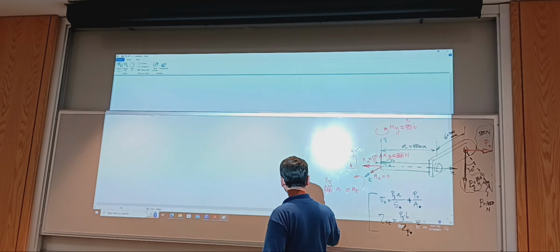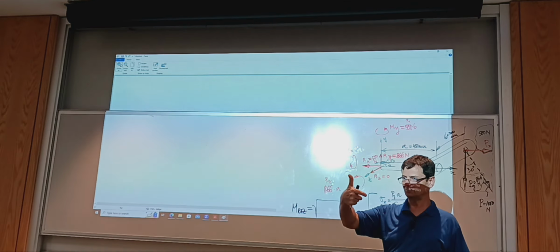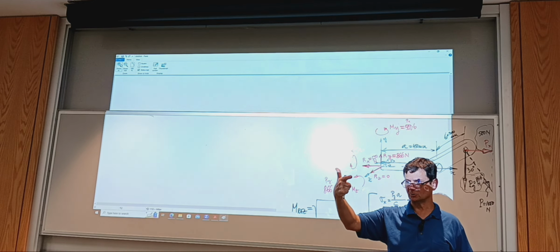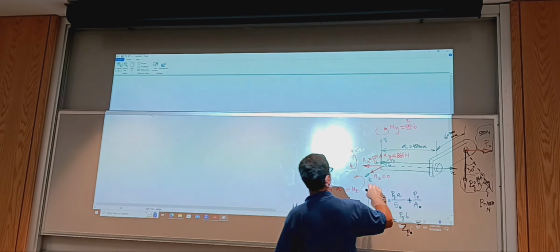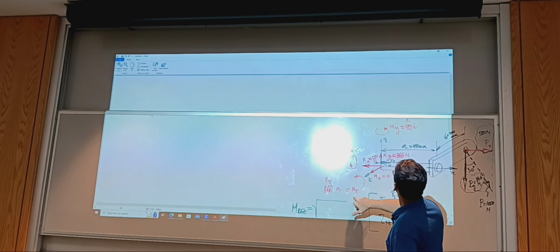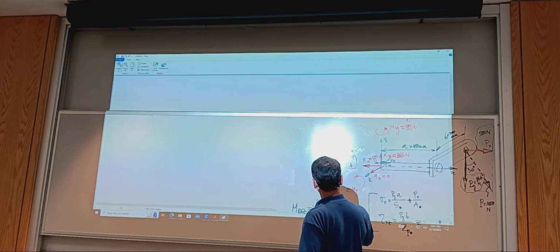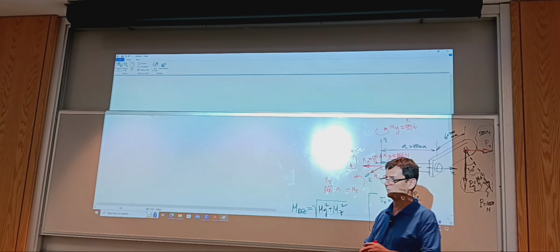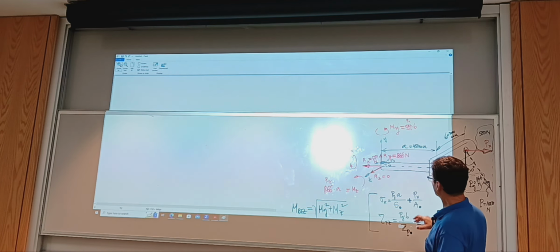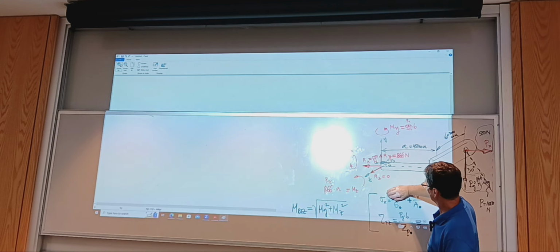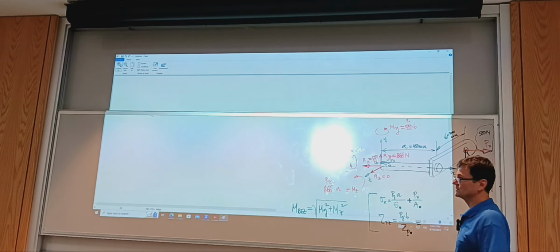So there will be a resultant moment, which is easy, you just sum the moments as orthogonal vectors, right? If you have two orthogonal vectors, how do you get their magnitude? First of all, which are the vectors? It's Mz and My. So it'll be the square root of My squared plus Mz squared. You've seen this before, two orthogonal values, Pythagoras theorem. This will be the maximum moment that will go in evaluating sigma. So this vanishes, you'll have this instead, and everything else the same.